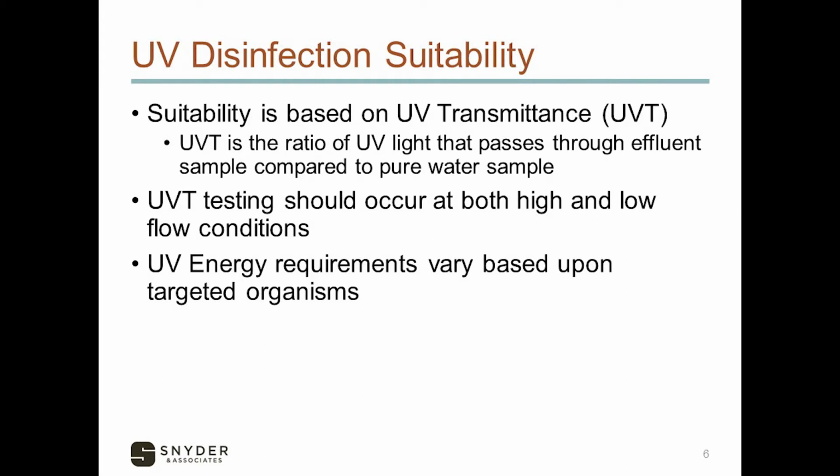Generally speaking, however, effluent will be clearer, providing higher transmittance values at higher flows than at low flows. And it's usually due to rainwater. Anybody have leaky sewers? Yeah, most of us have seen that. So how much energy is required if we do use UV? Let's pick a few important ones. How about cryptosporidium? We all know that that's a particularly difficult organism. And you can see that there are values there that we have to meet.